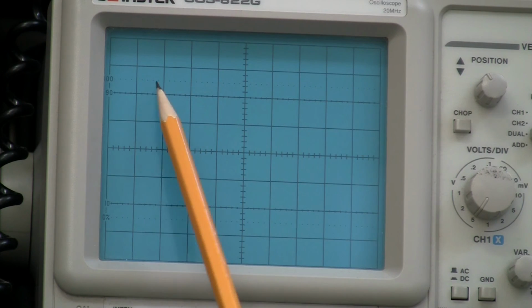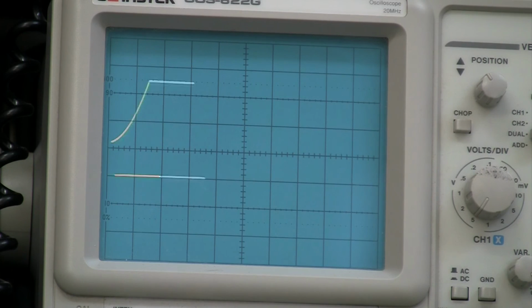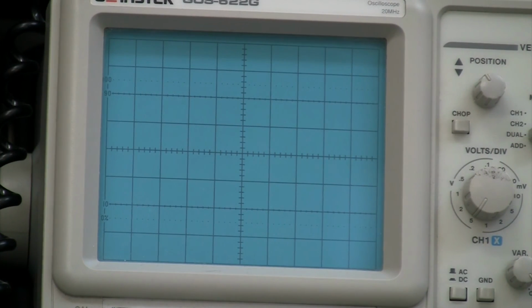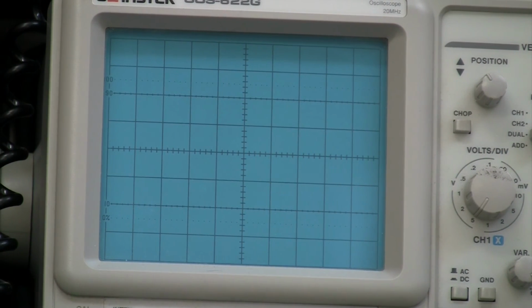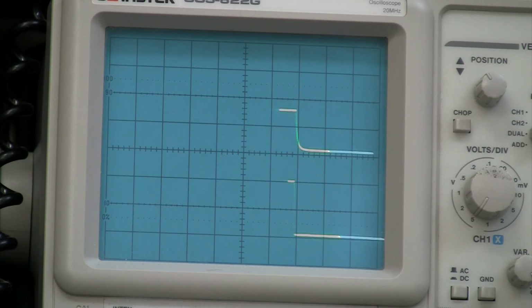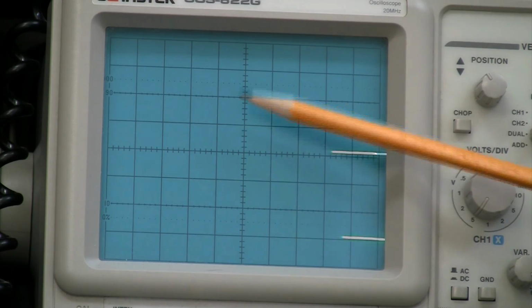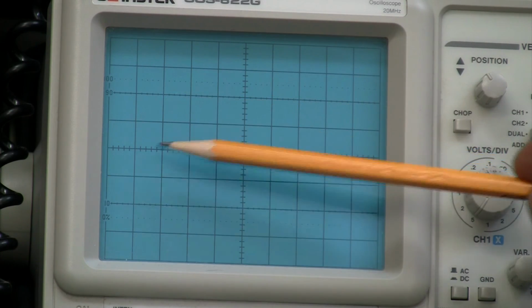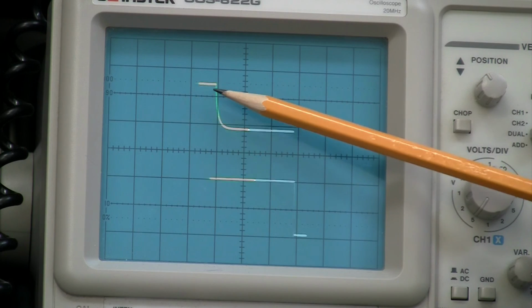Now to adjust this time is actually a very complicated set of things, because if you remember, we're clipping a waveform. So to make that time shorter, we have to reduce the control input level on the Q108 amplifier, which I'll do now. So it's not clipping as much, and as I do that, you can see that segment is narrowing. And also this slope is getting more linear.